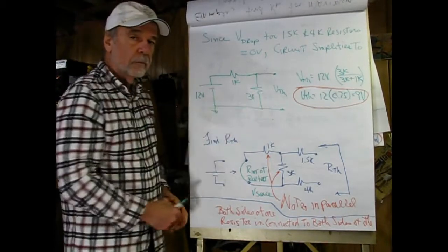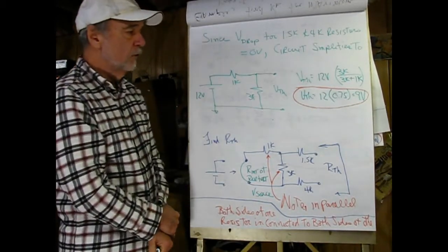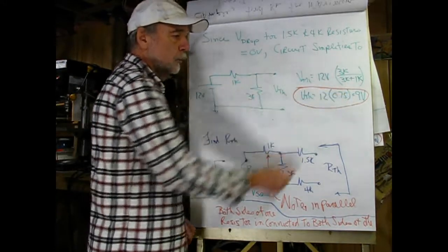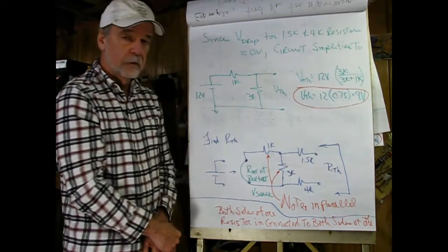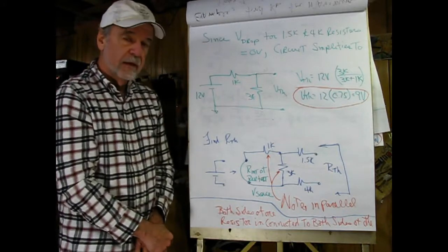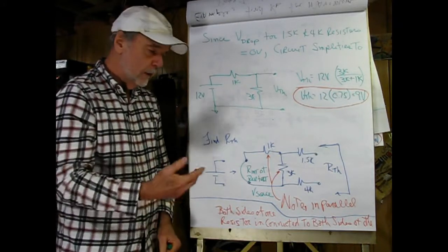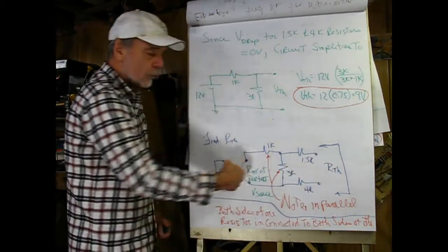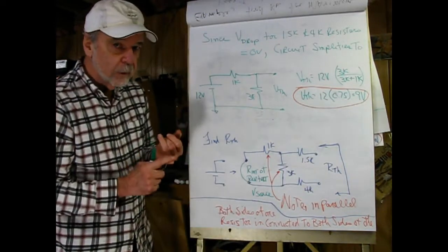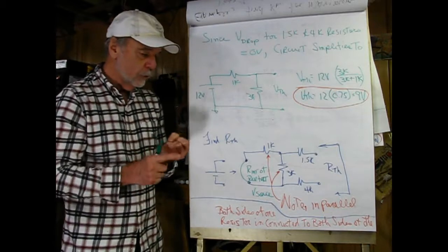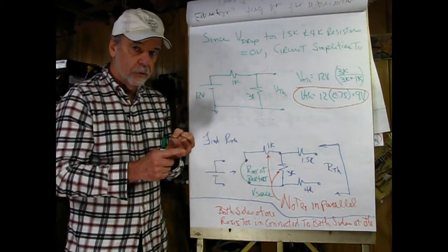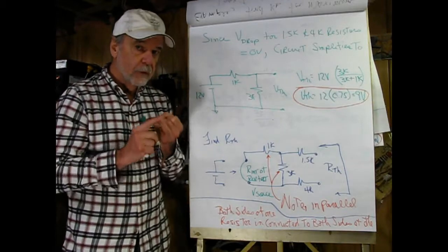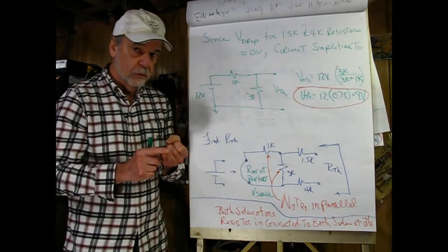to simply this. Applying voltage divider is what we see here, and we end up with a VTH equal to 9 volts. Easy enough. Now we have to find RTH, that's the Thevenin equivalent resistance, looking into the source. Now what you have to know here, and this is important, is the internal resistance of our voltage source is going to be 0 ohms, and if it were a current source, the internal resistance is infinite.